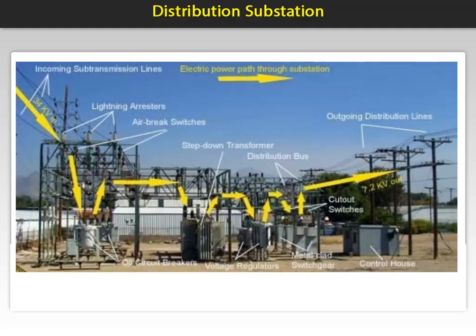The number of breakers depends on the load capacity and the needs for distribution feeds. The load side of these breakers are connected to a bus configuration and fused cutout switches on a rack assembly. It is from here that the power is connected to the outgoing distribution line poles. Coming up, we examine these components in more detail.